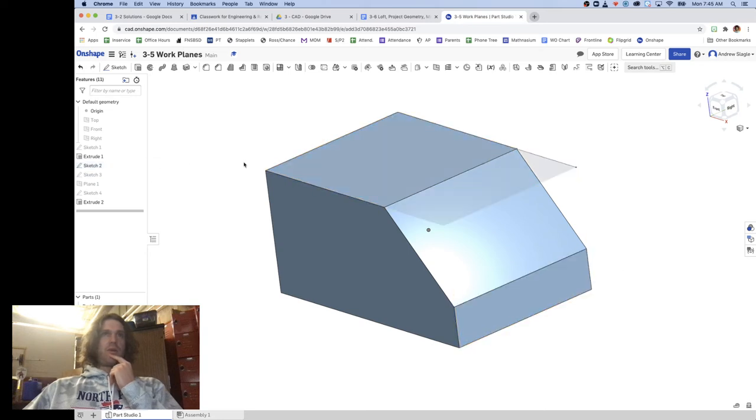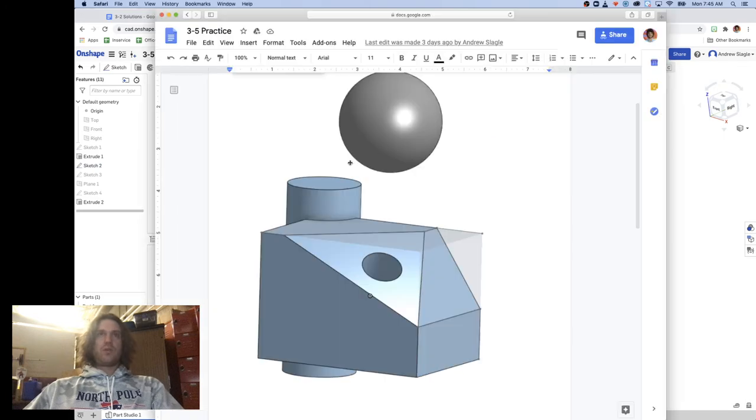I take that back. I am going to go into sketch 2. I'm going to add a line to sketch 2, and you'll see why in just a second. There's another plane that you can draw called the 3-point plane. It turns out if two lines are parallel in three-dimensional space, we can have a plane connecting them. If you have 3 points, you can create a plane, and I would say the 3-point plane is just so unbelievably useful for making those removals. So I'm going to draw a line in sketch 2.